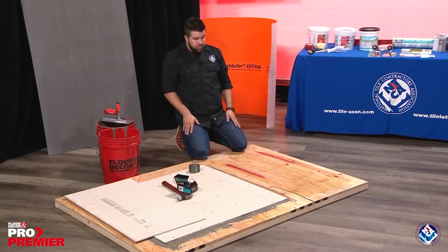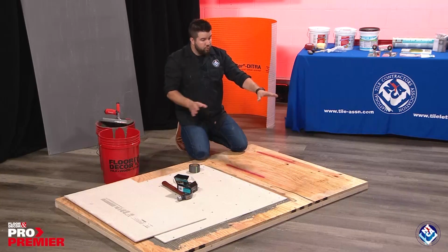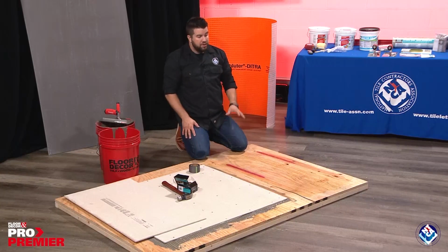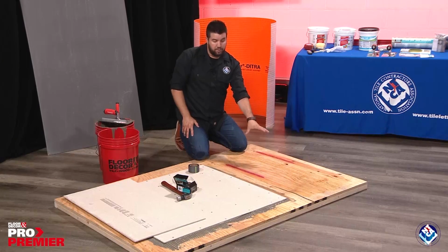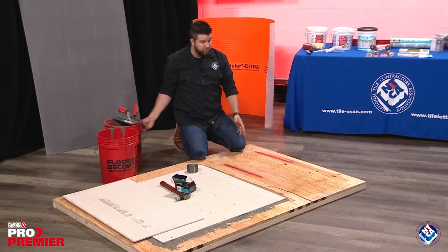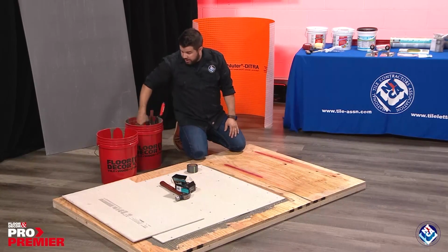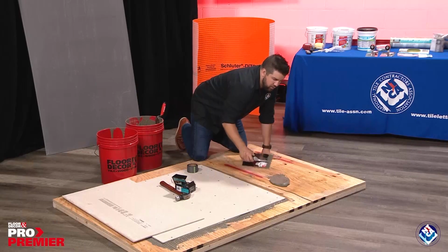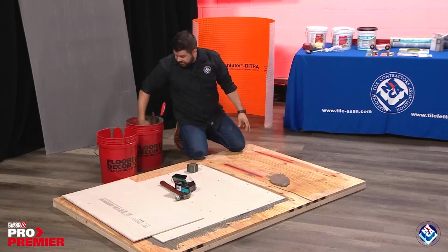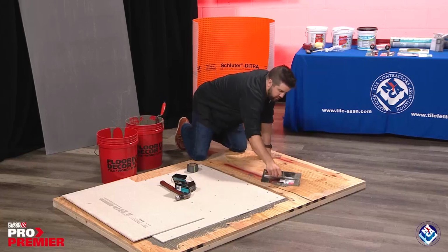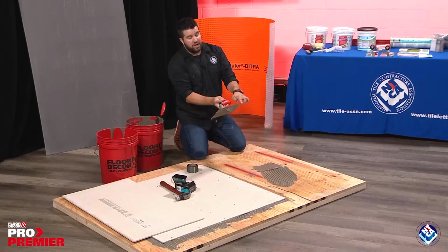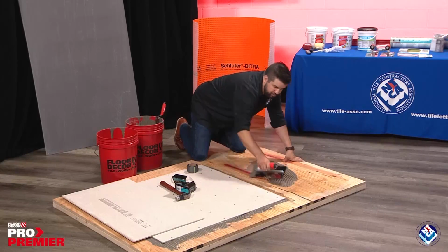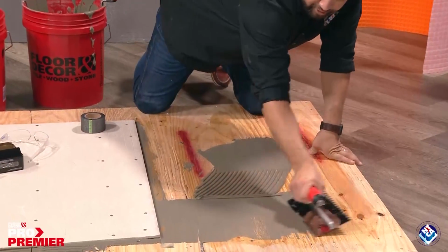So we flattened our floor, we've added any patch that we needed to add, we've wiped down and removed the dust, and we've given our plywood subfloor a drink of water, we've hydrated it. We are now ready to add some thin set. We don't want to just put thin set on there and start troweling with our ridges. We don't want to just go straight to that motion. We want to always use the flat side of our trowel first, and what we're doing is burning in or keying in our mortar.